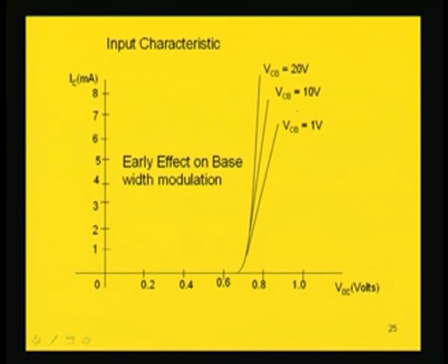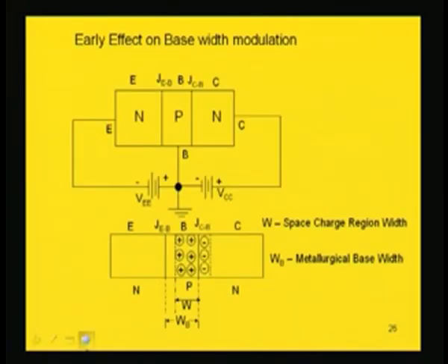If we go on increasing the reverse bias potential, what will happen is that, considering the base width of this transistor, there are two junctions, one is forward bias, one is reverse bias, but this base is lightly doped. So, the reverse bias junction practically penetrates into the base region more than the collector region, because the base region is lightly doped and so it will be penetrating more. So, mostly the space charge region will be in the base region.